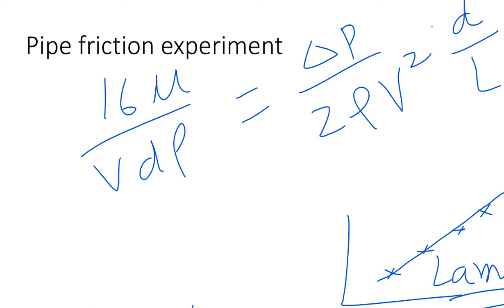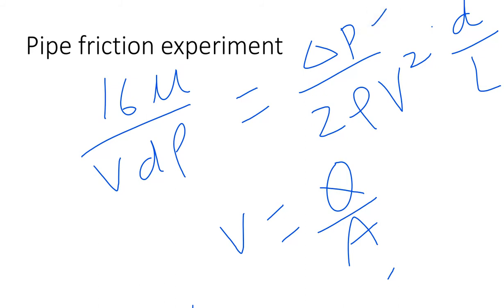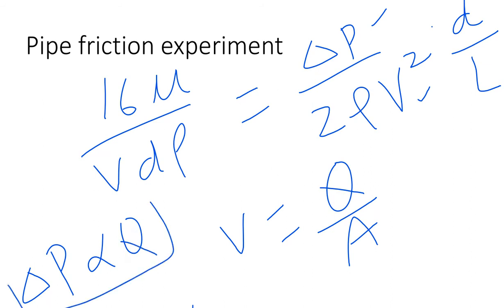Okay. So now V is also a function of Q: V is Q over area. We're trying to get delta P and Q. So where is Q? Q is here also. So replace this, and then establish a relation between delta P and Q. You should get delta P, you will have other factors, but proportional to Q. I leave it for you. This is for laminar.